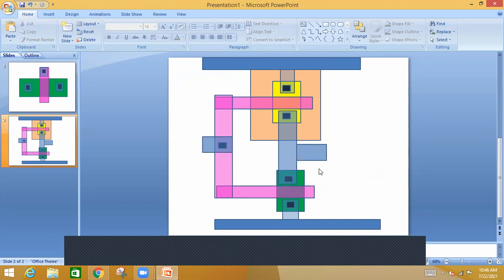Okay, so in this layout and whatever layout you have been shown, now everywhere you have to put the dimensions, where it should be 2 lambda, where it should be 3 lambda. That is called the layout of a CMOS inverter using lambda rules. Okay, so you got it?